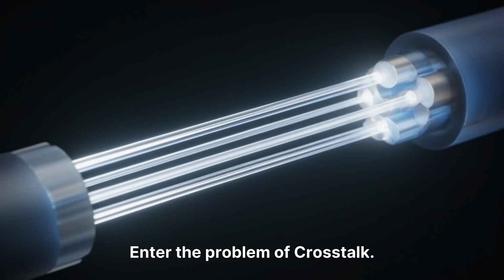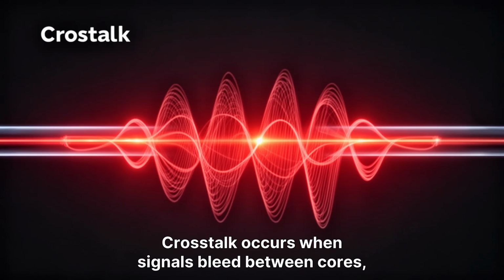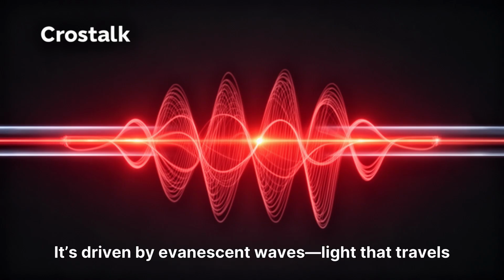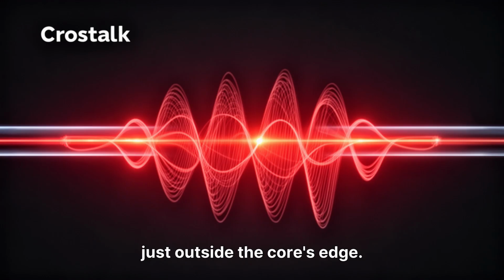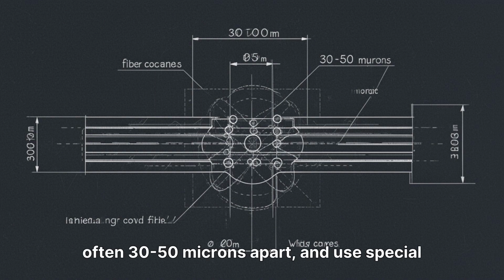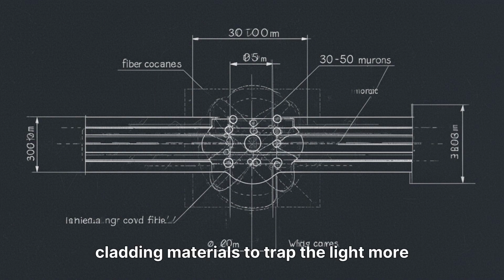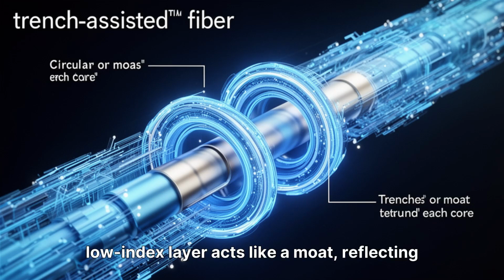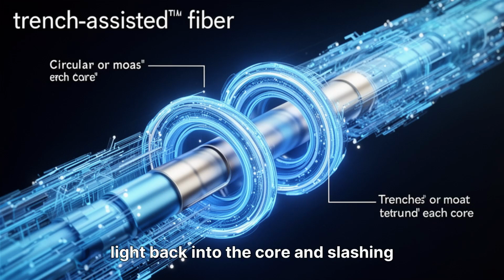Enter the problem of crosstalk. Crosstalk occurs when signals bleed between cores, causing data errors. It's driven by evanescent waves, light that travels just outside the core's edge. To combat this, engineers space cores carefully, often 30-50 microns apart, and use special cladding materials to trap the light more effectively. Advanced designs use trench-assisted cladding, where a low index layer acts like a moat, reflecting light back into the core and slashing crosstalk levels.